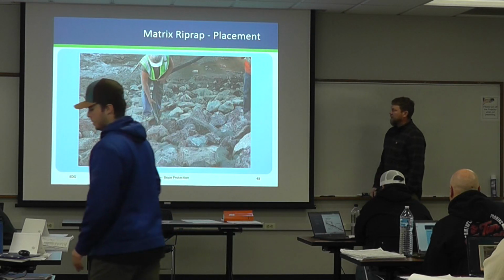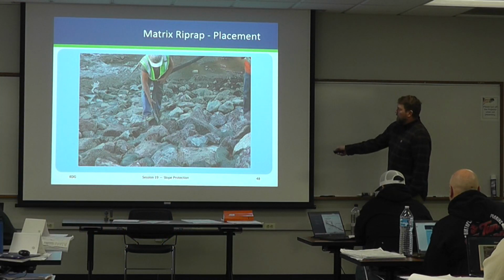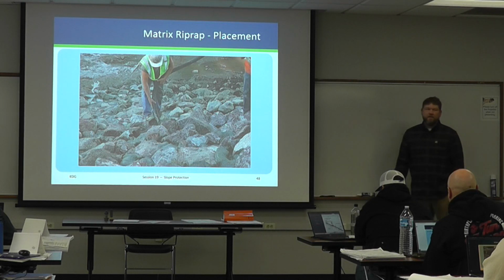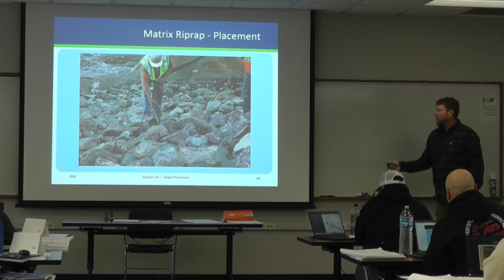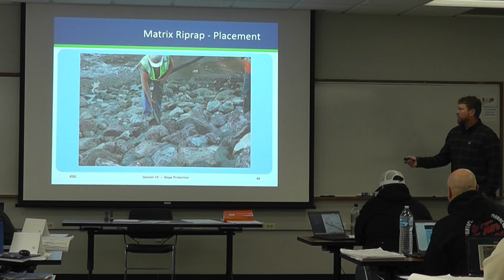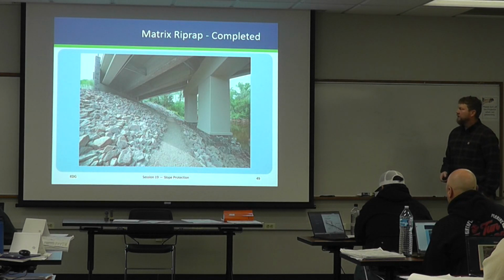So here's a picture of it being placed. You can see there are voids still in here. If fully grouted, you're not really going to see much of that riprap at the end. We're just filling the voids in between, placing with the hose. And then this is the finished product.